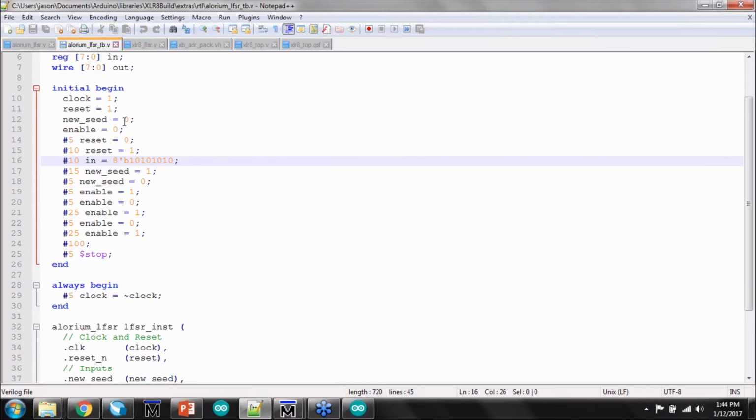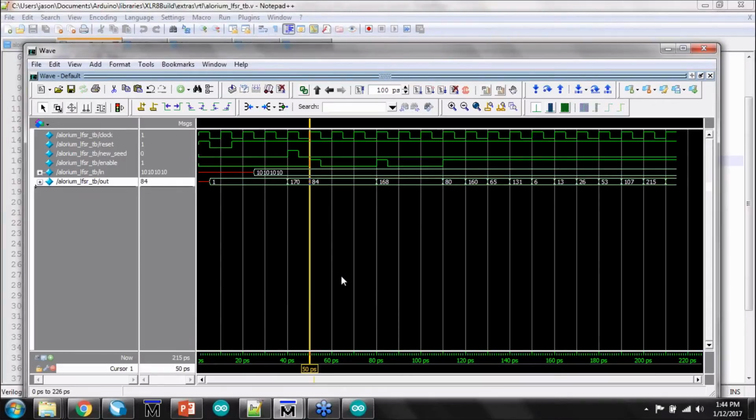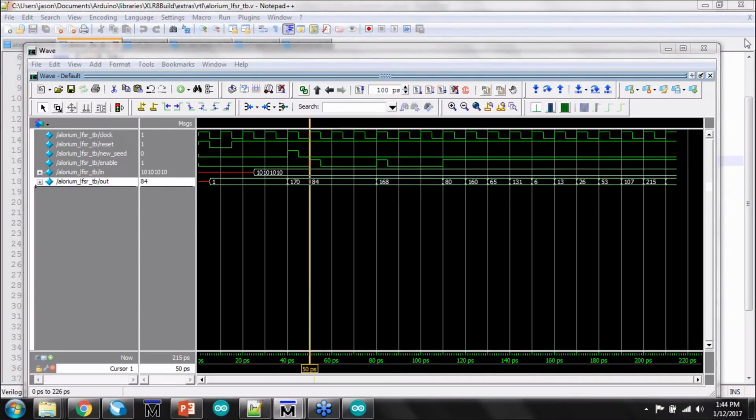you can dive way down deep into your code and look at every single signal that's there, and figure out why something isn't working the way you'd expect before you actually have it on hardware on a bench. Because sometimes the things that don't work are buried way down inside that code, and it's really not clear if you're just measuring something at the outputs of a physical I/O pin, or it's not controlling a motor correctly. To be able to look at it at this level is extremely valuable in debugging your hardware before you're trying to do something in the actual lab or running it on a benchtop. So that's one of the real values of doing this. And I apologize, Brian, for the interruption. I just want to make sure I mentioned that.